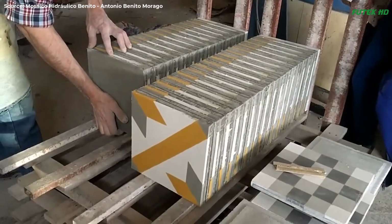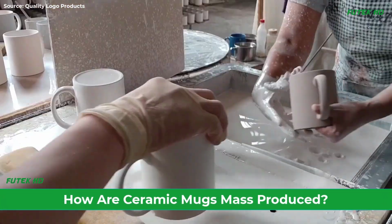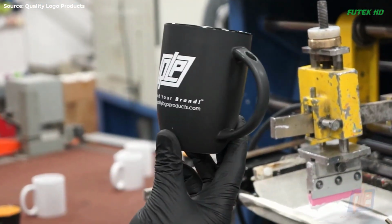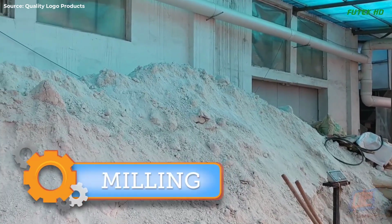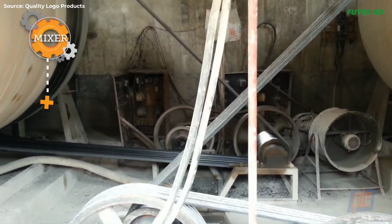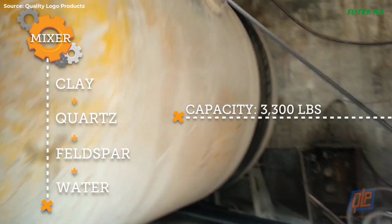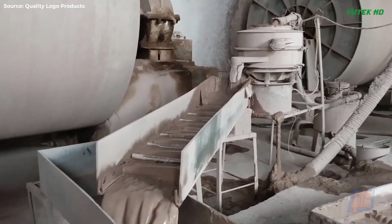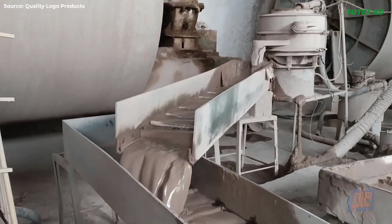The process begins with the preparation of raw materials. The primary raw material is clay, which is fed into a grinder and pulverized into a fine clay powder. This clay powder is then combined with other ingredients, such as quartz, feldspar, and water, in a mixer. The mixture is refined over a period of about 15 hours to create a homogeneous clay slurry.